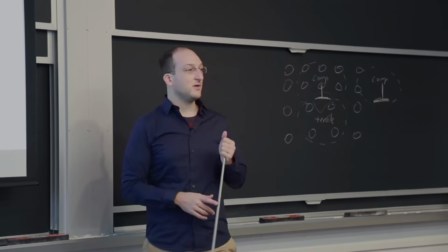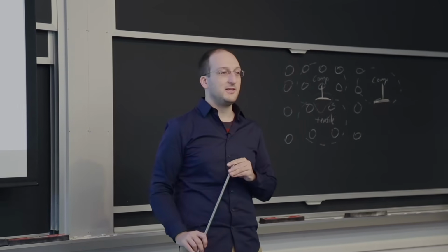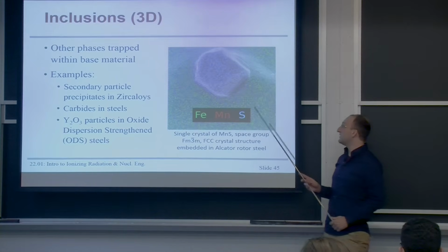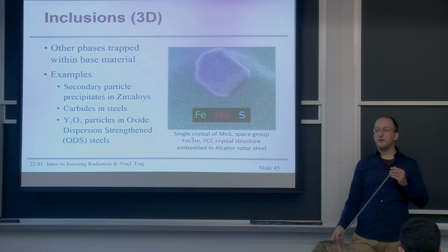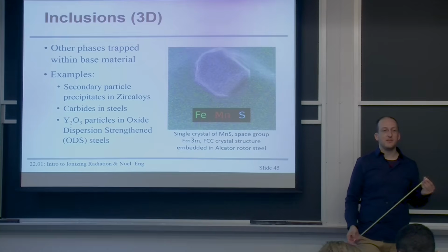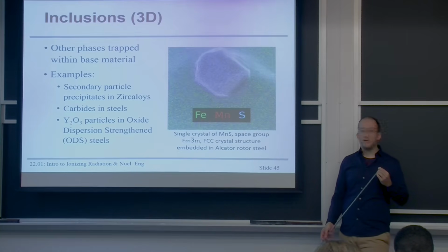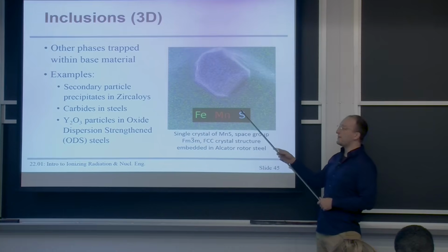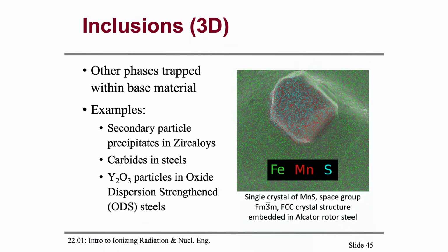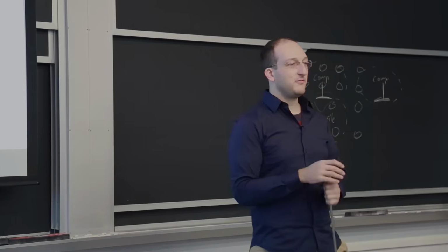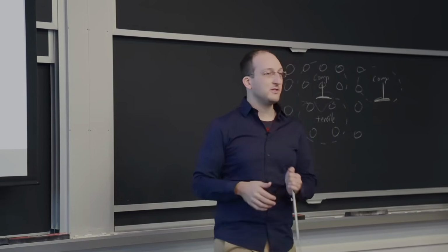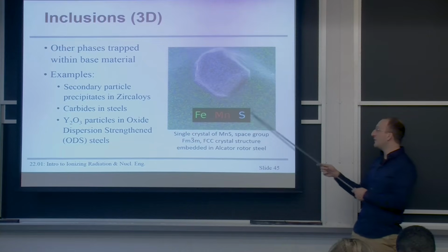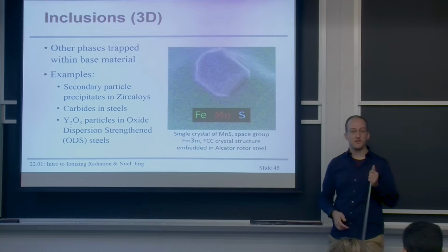We did a lot of this work to find out that the structure hadn't really changed since 1954 when it was made. What we did also see is we could pop out little precipitates of manganese sulfide. There's always sulfur in iron, and sulfur tends to be a bad actor when it comes to material properties. You throw manganese into iron to scoop up that sulfur in the form of these little precipitates or inclusions, which we were able to see perfectly when we did an X-ray map, just like the one we did after the first exam. When we were looking at Chris's copper-silver alloy, mapping out where the copper and silver are, I made this image the same way, mapping out where there is iron, manganese, and sulfur. That's how you can tell what it is.